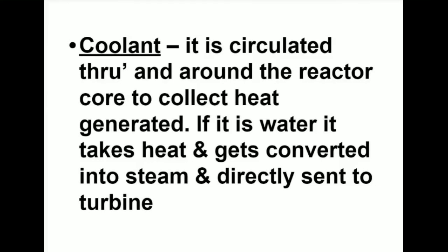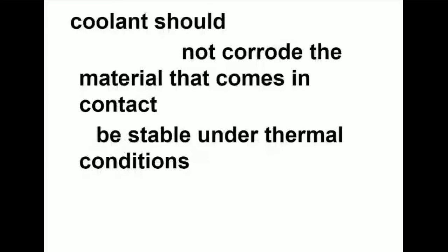And coolant, it is circulated through and around the reactor core to collect the heat generated. If it is water, it takes heat and gets converted readily to steam and it can be directly sent to the turbine. Otherwise we can use heavy water, molten sodium, etc. as coolant. Coolant should not corrode the material that comes in contact. It should be stable under high temperature conditions.